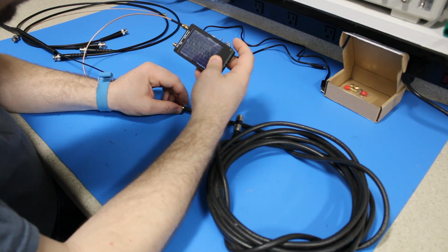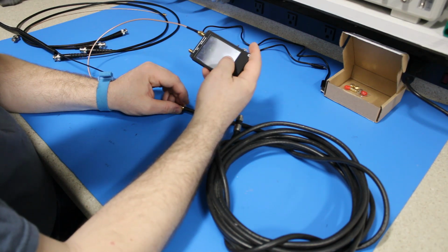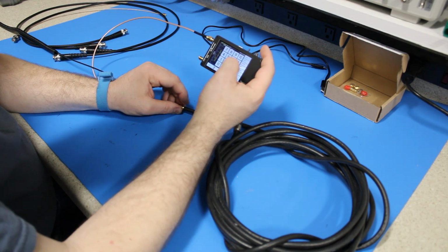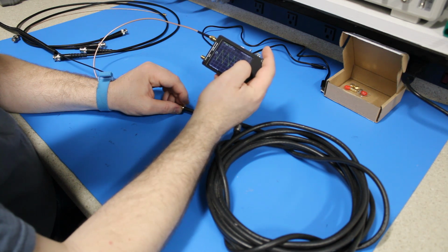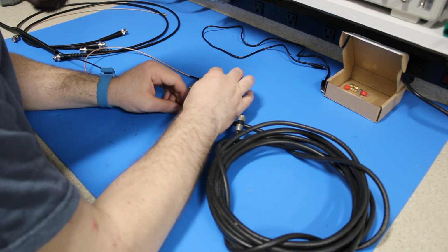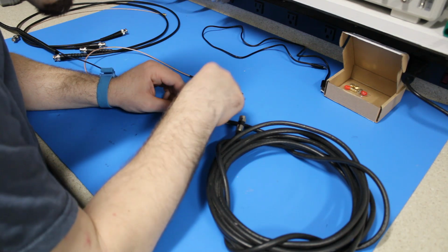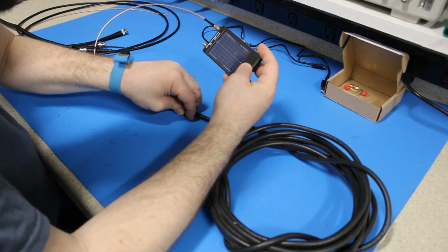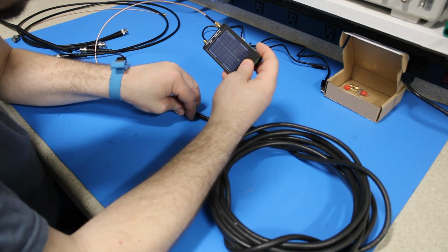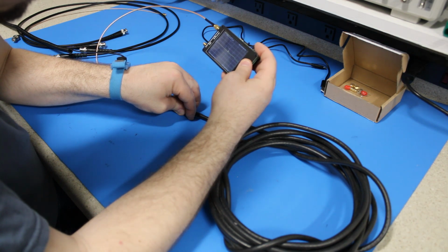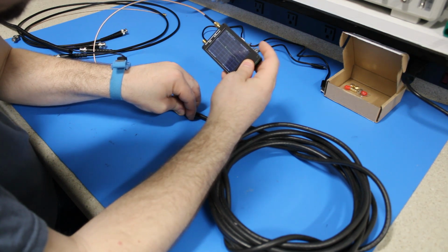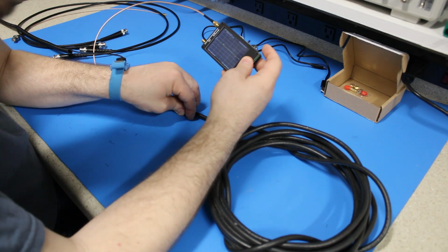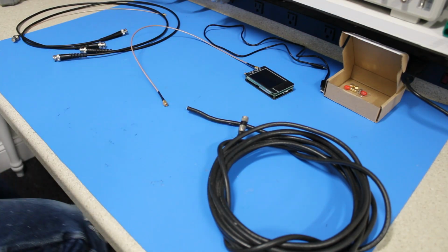So we are at approximately 21 megahertz, and what we're going to do is adjust the stimulus one more time to try to get a little more accuracy. We'll say 23 megahertz on the top end, and on the low end we'll do 20 megahertz. Alright, now this will give us an opportunity to really dial in where that phase crosses 0. There it is, 20.87 megahertz. Alright, so I'm going to take a note of that.